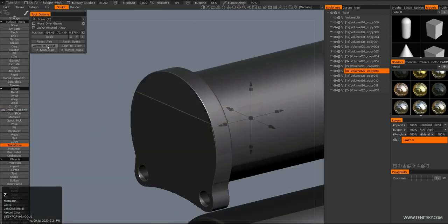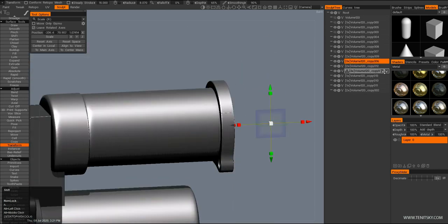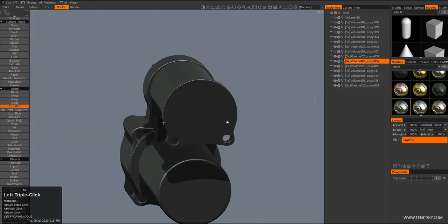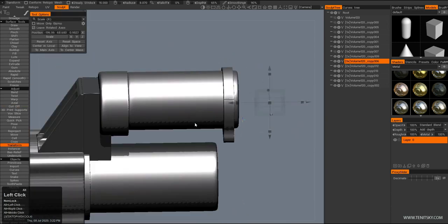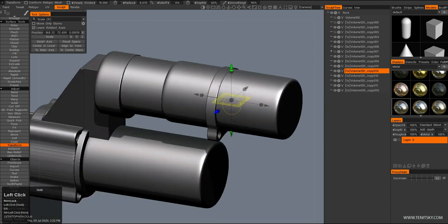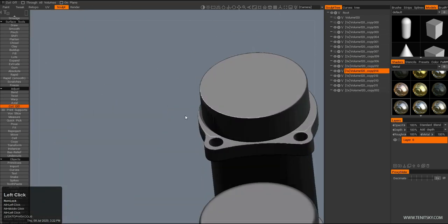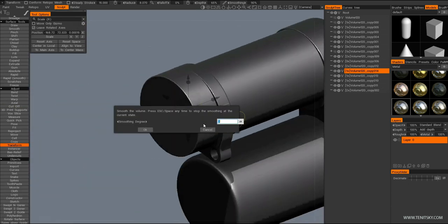And this is a really recurrent thing in this hard surface modeling, in just the voxel modeling I do, is that I'm reusing the parts constantly, and you can always combine voxels with voxels. You'll get a perfectly normal voxel mesh. So usually, sometimes the easiest way to fix something is actually just to merge two volumes together.